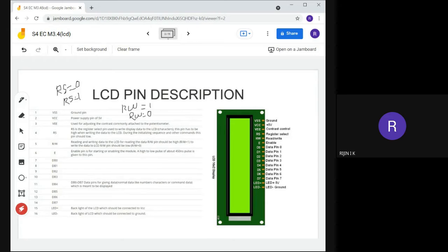VSS is connected to ground, VCC connected to power supply, VEE for adjusting the brightness, RS for selecting the register. There are 2 registers: what are they? Command and data register. For selecting the command and data register, we set the corresponding value. And the RW pin is for reading and writing data to the LCD.